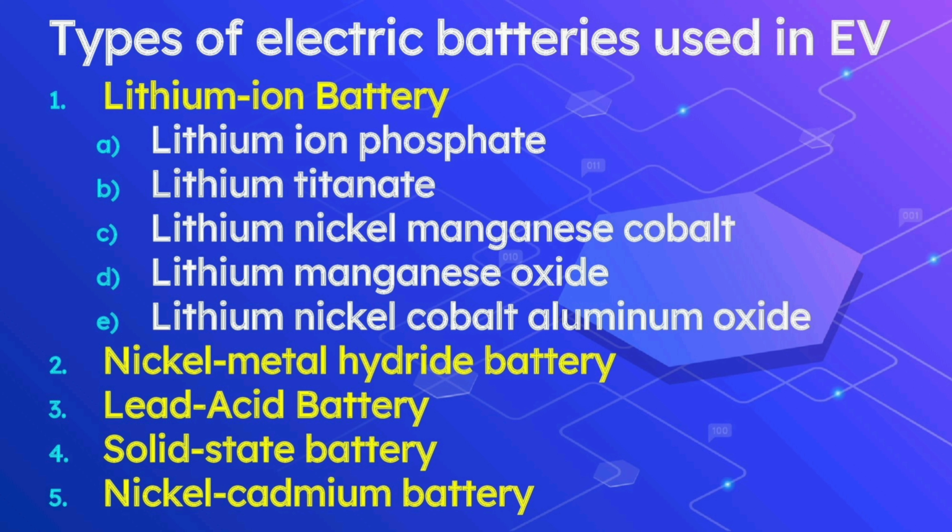Next one is the performance. This measures how well the battery works over a wide range of temperatures. Most batteries are sensitive to heat and cold and require climate control. Heat reduces the life and cold lowers the performance temporarily. Lifespan reflects the cycle life and longevity, and it is related to factors such as temperature, depth of discharge and load. Hot climates accelerate capacity loss. Cobalt-blended lithium ion also uses a graphite anode that limits the cycle life of this battery.